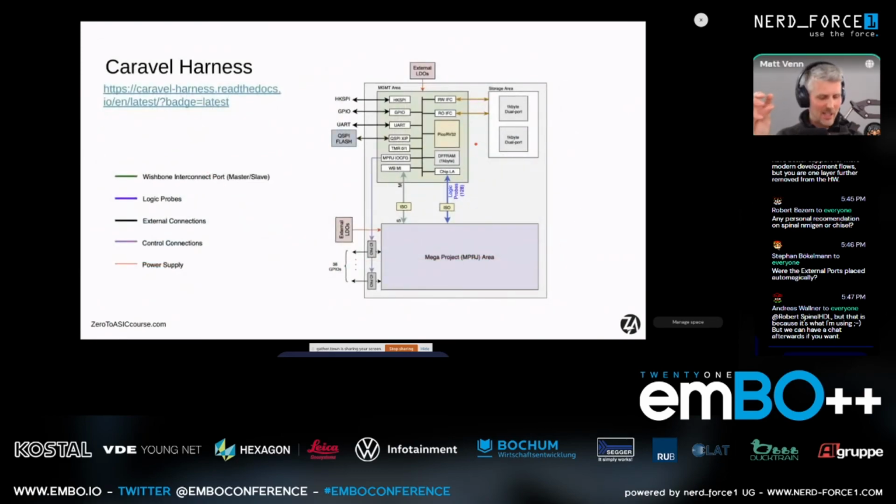So we made this tiny little 7-segment display, and that is fitted into 100 by 100 microns. And we've got 10 square millimeters. So not 10 by 10, because that'd be 100 square millimeters, but 10 square millimeters, more like 3 by 3. So we could fit about 8,000 of those 7-segment counters in the space that we've got to play with in the tape out. So there's a huge amount of space to experiment with.